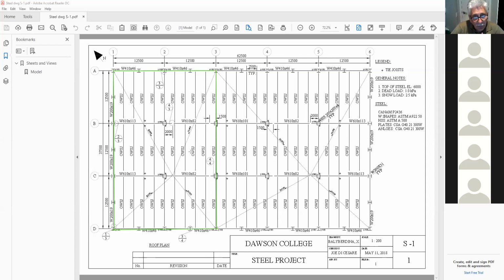And there's also a maximum slope when it comes to drain pipes. I don't know if you guys know that. There's a minimum for drain pipes, and there's a maximum for drain pipes, because if the velocity is too high, all the solids stay behind and only the liquid goes through. I don't know if they talked about that.